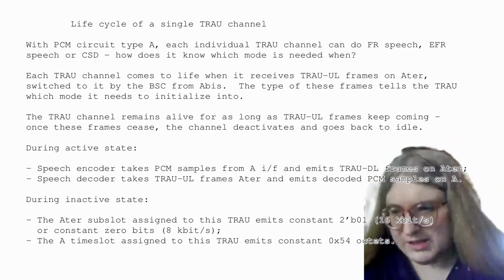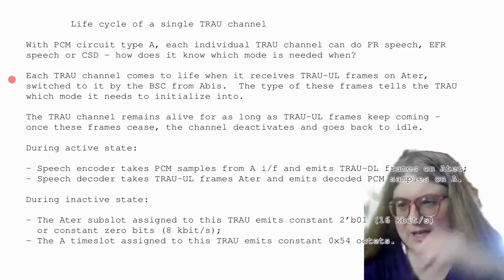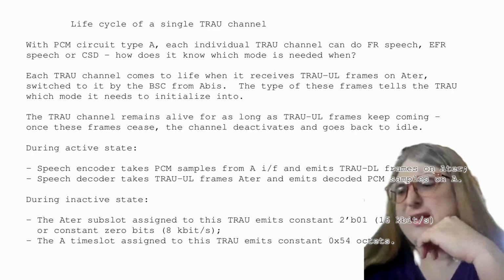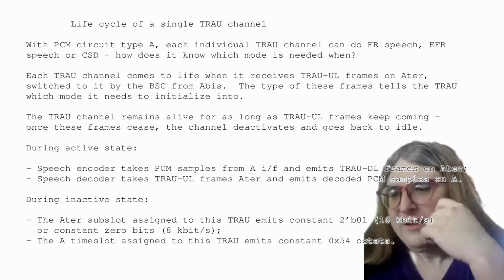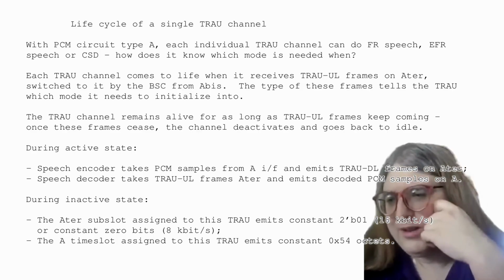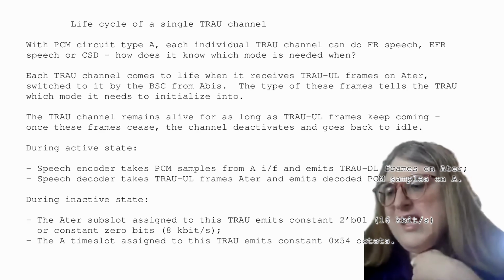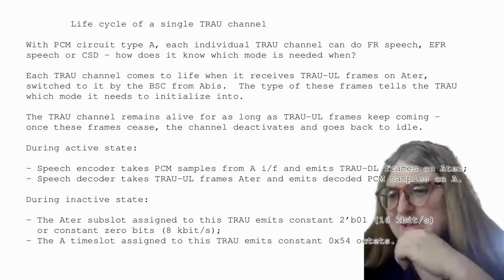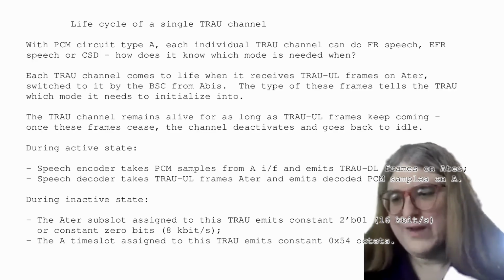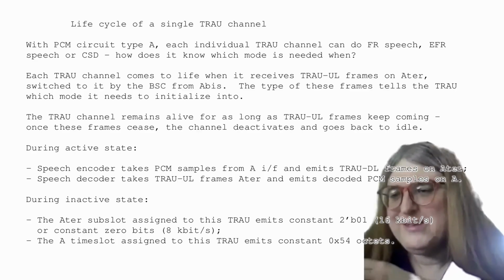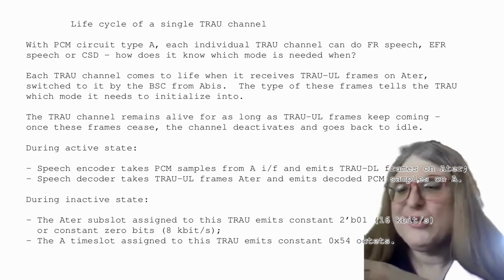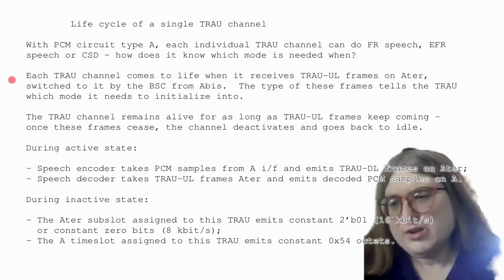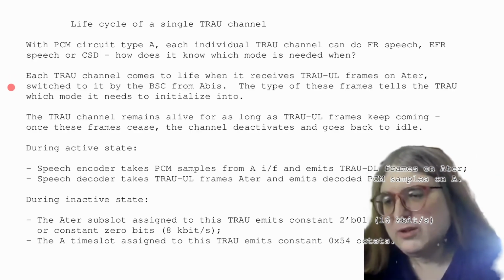So let's see. All right, so this is what I was getting into: the life cycle of a channel. It bears reminding that the GSM 08.60 spec that defines the format of TRAU frames is not titled TRAU frame format. The title of the spec is In-band control of remote transcoders and adapters. And the in-band control part is really critical, because of the management interface that we covered.